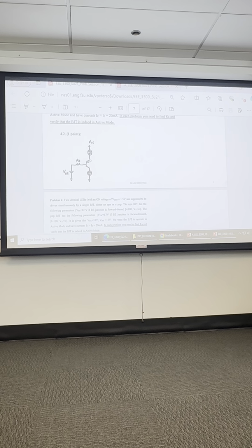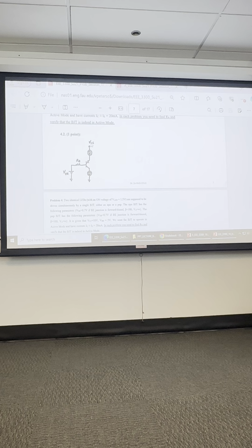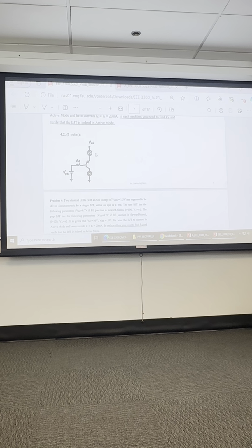So, what's the voltage on the emitter here? 10 minus, and we note this because we don't want to overlook if a problem appears with the LED in the opposite polarity, and then the transistor would be cut off. And now we're going to spend 15 minutes and finally realize the LED was actually backwards. So with the LED, current should flow from the battery to ground. The LED appears to be in the right polarity, so the emitter here will be 10 minus 1.5.